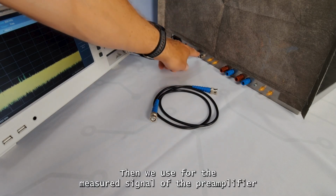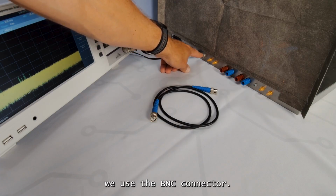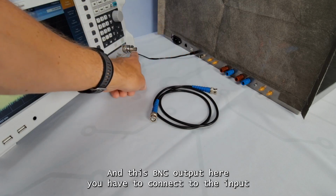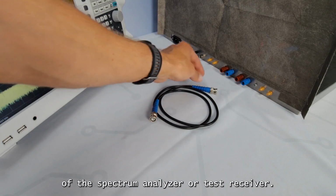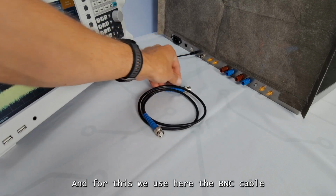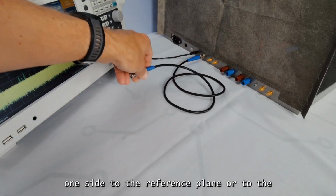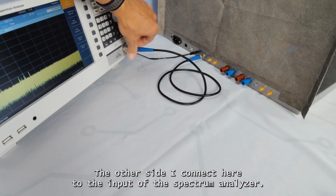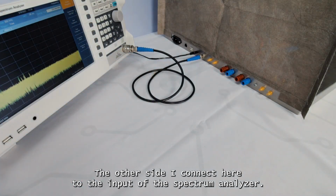For the preamplifier measuring signal, we use the BNC connector, and this BNC output you have to connect to the input of the spectrum analyzer or test receiver. For this we use the BNC cable. One side to the BNC connector in the reference plane, the other side I connect to the input of the spectrum analyzer.